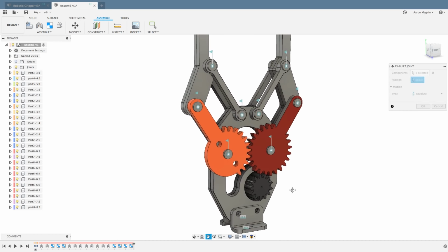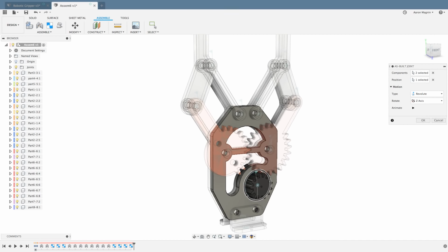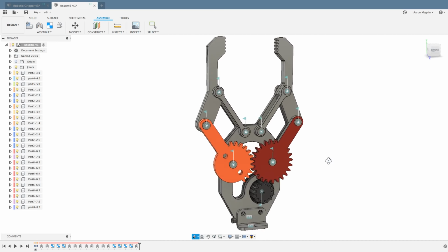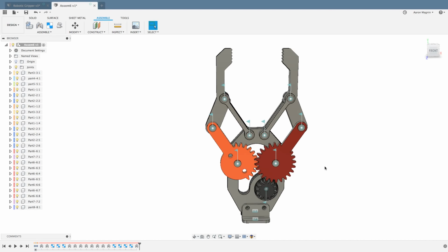That's a nice way to be able to find the center of something that maybe doesn't exist. Maybe I want to select the center of this, but I'm having difficulty selecting it. Holding command after I've highlighted that model edge will enable me to select that a little bit easier potentially. Okay, so I think that is looking pretty good.